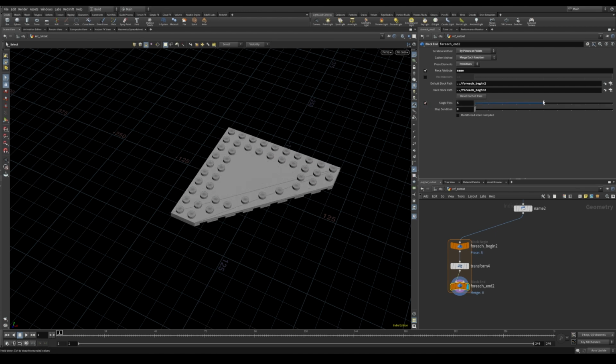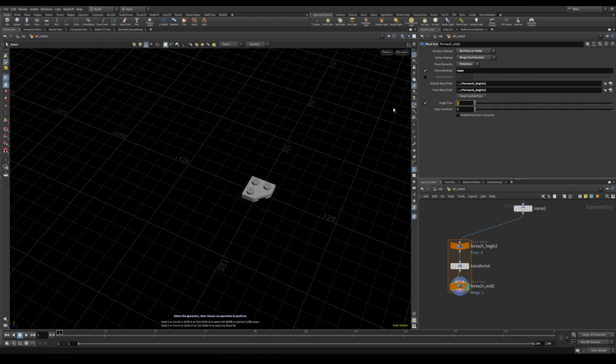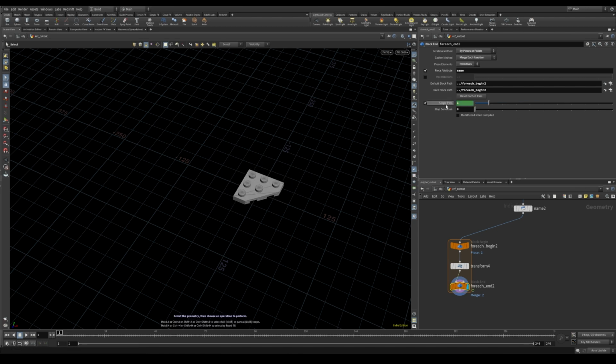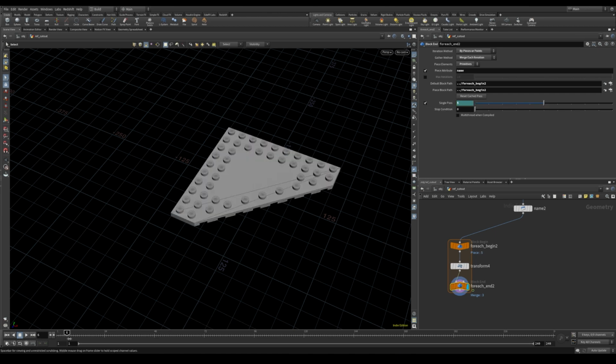Basically, here you can cycle through the different for loop iterations, and we can use the @frame expression. So now the number here will be the current frame, and by scrubbing the timeline, we cycle through the different pieces. Currently, we are missing the 0 pass because our timeline starts from 1, so either you change the timeline to start from 0, or we can simply add a -1 here. So now we're starting from pass 0, and we are cycling through the different pieces.